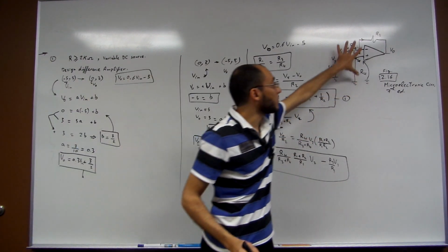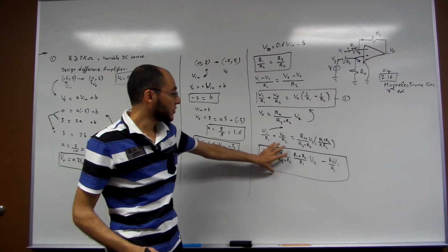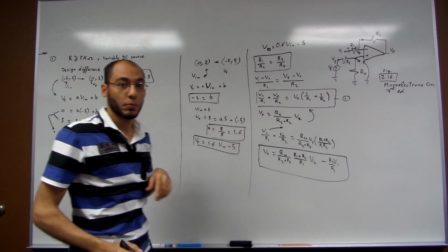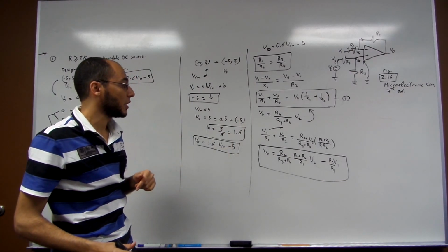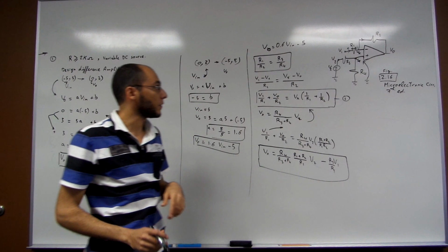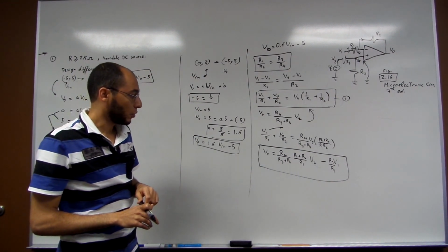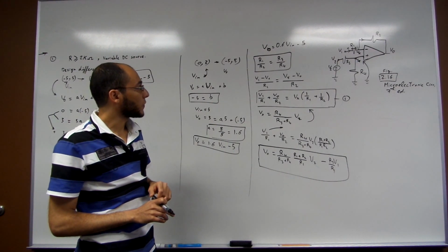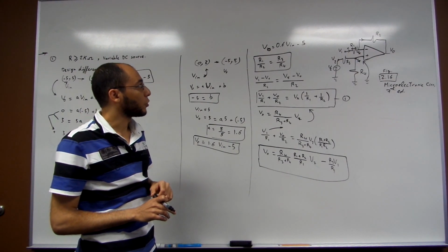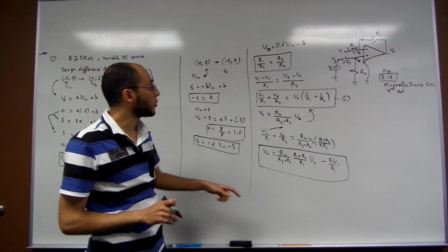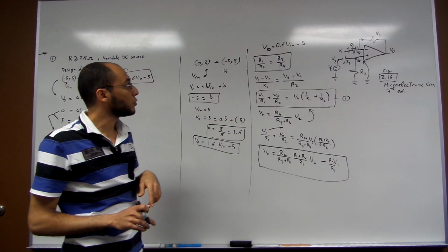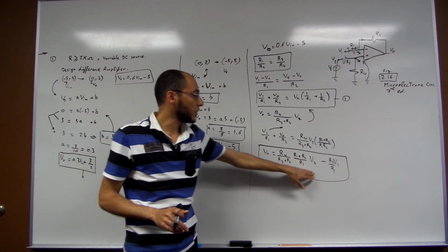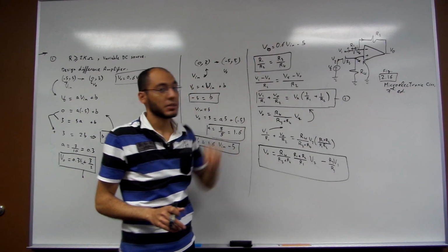This equation describes how this circuit performs, and my duty is to put this equation in this form so that I can somehow find the numbers that I want, which are the values of the components. Actually, I'm going to solve using the method of comparison of coefficients. I'm going to compare the coefficients together, and choose the numbers for R4, R1, R3, R2, V2 and V1, so that I can implement this equation.